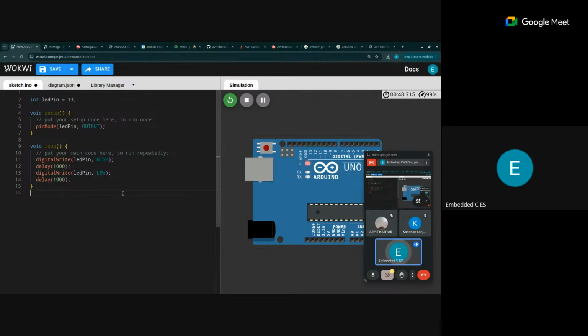So this is how you usually do things. You know that this sketch.ino that is present in every Arduino folder, like the Arduino Sketch, as I used to call it, is actually C++ code. What Arduino does is some kind of pre-processing, and it runs setup only once and then loop. After the pre-processing, the Arduino file gets converted to a CPP file, which will have a main function, as you know, like C, right?